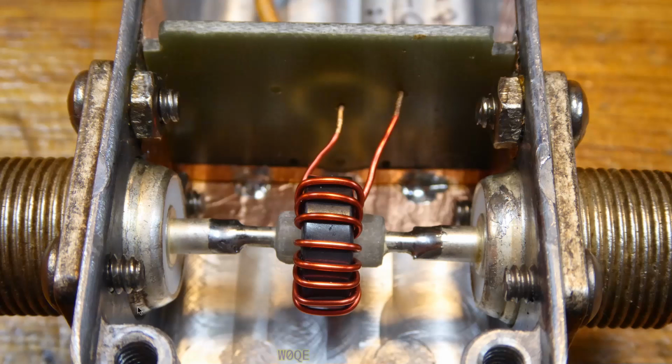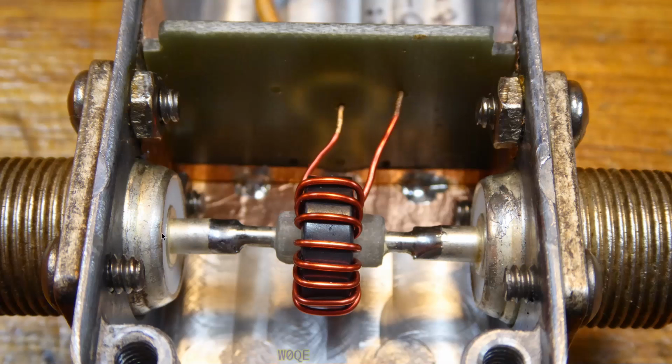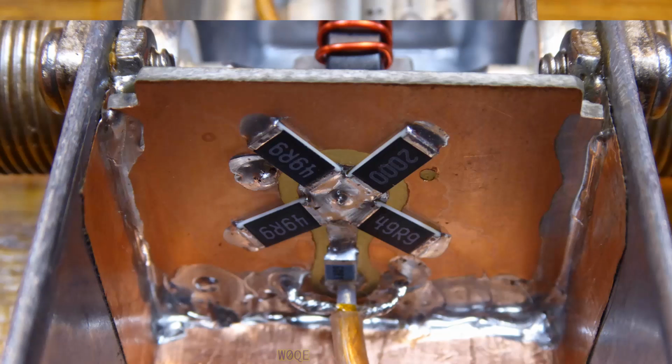It's about 1 1/8 inches high, and it's a little less than 4 inches long. And this is a piece of 12 gauge wire between two Teflon SO239s. And here's my little toroid, which has 15 turns of number 22 gauge wire on it. Now you can't really see this, but there's a little circuit board on the other side here. The next picture shows the back side of that. Here's the toroid, and we're looking on this side.